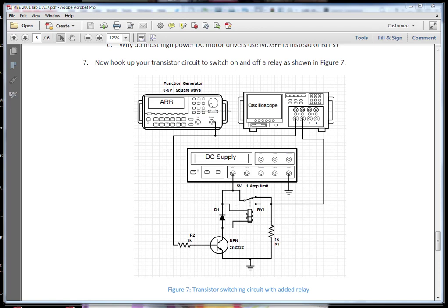So in this case, we're using this transistor to increase the current. I guess I'll mention too that the work you've done with op-amps so far, when you talk about a gain, we always talked about in 1001, it was usually a gain with regard to the voltage. Here we're talking about, with this type of transistor, a gain with regard to the current.